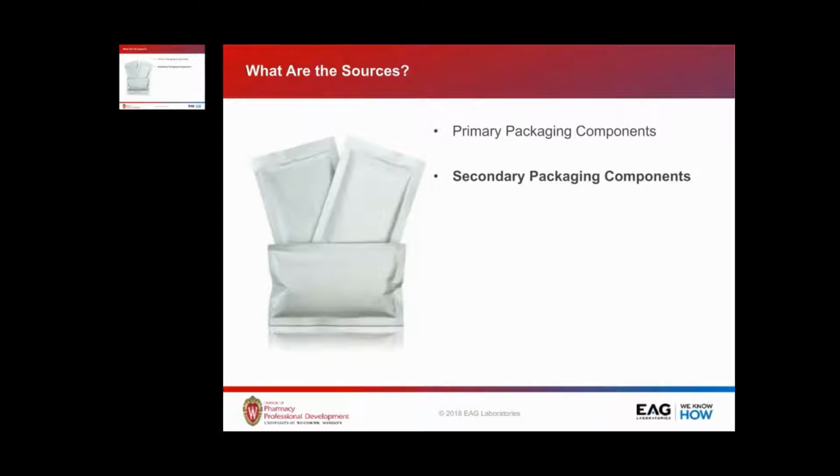Unfortunately, when you place those on certain polymer materials, the inks and/or the adhesives can migrate very aggressively right through your container closure system into your final drug product. So it's important to understand how the secondary packaging, how the labeling, plays into the potential sources of leachables.